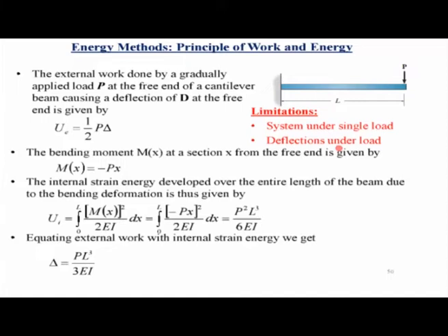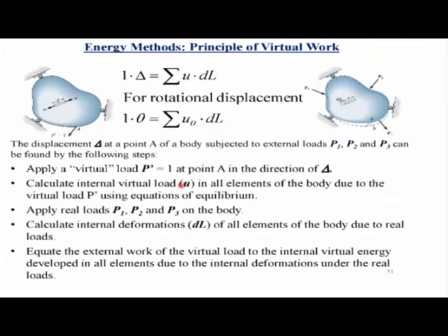So in order to overcome that limitation, the principle of virtual work has been introduced, which has a similar concept as the principle of conservation of energy, but there is a virtual work or a hypothetical load that is being applied, and the work due to that load is calculated. So let us look at this system, which is subjected to three different external loads, P1, P2 and P3.